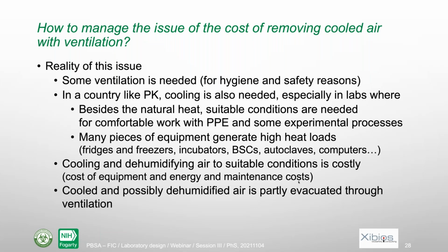Cooling and also the humidification of the air to suitable conditions is very costly. It's the cost of equipment, but it's also the cost of energy, which can be very high, and the maintenance cost. And of course, if you cool down the air at high cost and you ventilate, you will evacuate that air. So I only explain, it's not the answer, I only explain the question and why it is such an important question in laboratory design.